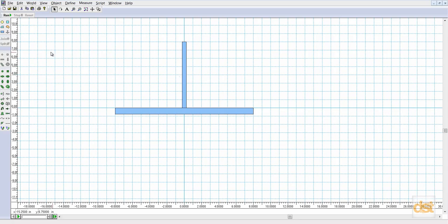The last thing we're going to do is draw the beam in here. Again, click on the rectangle tool, click at some arbitrary position, and I'm watching the W readout down on the bottom left corner. I'm interested in getting this at 12 inches. The height, again, arbitrary. I'll leave it at 0.5 and click. So there overall I have a 12-inch beam right there.